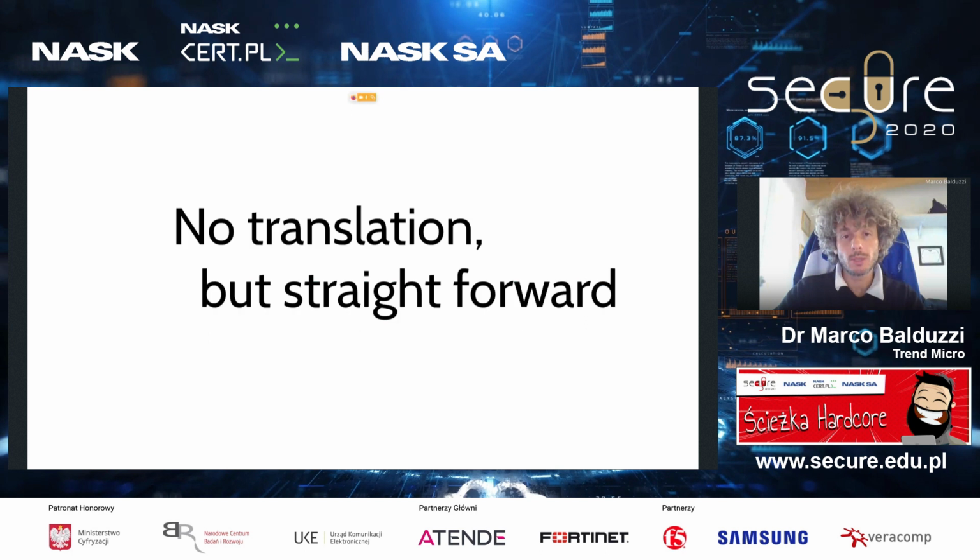So in this specific condition, what the device does wrongly, instead of dropping the packet or correcting the value of the header, is basically a straightforward forward of the packet as it is. So it's never dropping the packet or correcting the packet, and it is not translating the packet from Modbus TCP to RTU, but is basically forwarding the packet as it is.